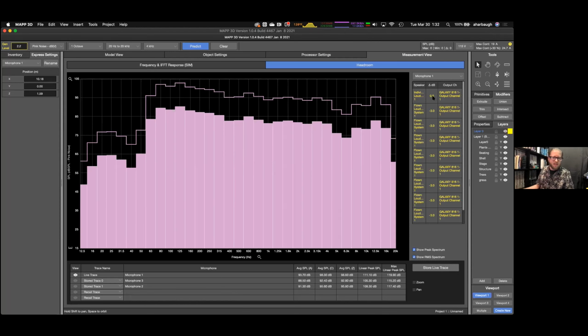And that moved everything into the yellow, but now I can see on that X22 loudspeaker, I'm hitting the limit of that loudspeaker, and that's the limiter kicking in, and it's probably not going to give me much more SPL that I would consider usable for the system. And then the Lena array still has 3 decibels left over. So even just from this table, I can see that my Lena can go about 3 decibels farther in headroom than my X22.